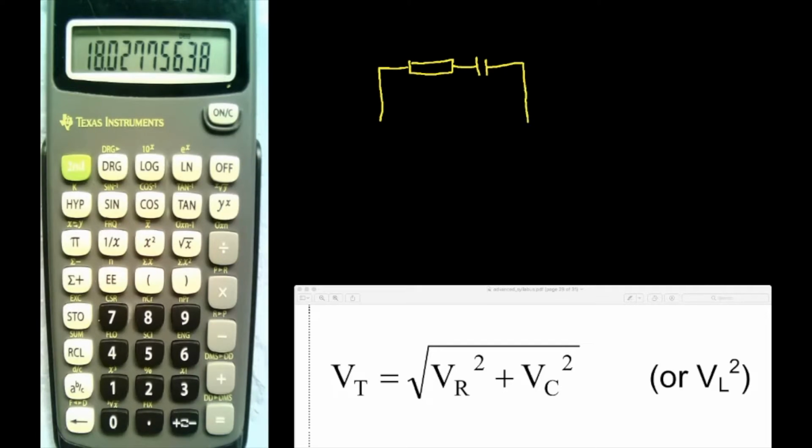now going aside a minute, if that had been a resistor and a resistor, and if I'd had 2 volts across that resistor and 3 volts across this resistor, then Mr. Kirchhoff tells me that the voltage here was simply the 2 plus the 3.